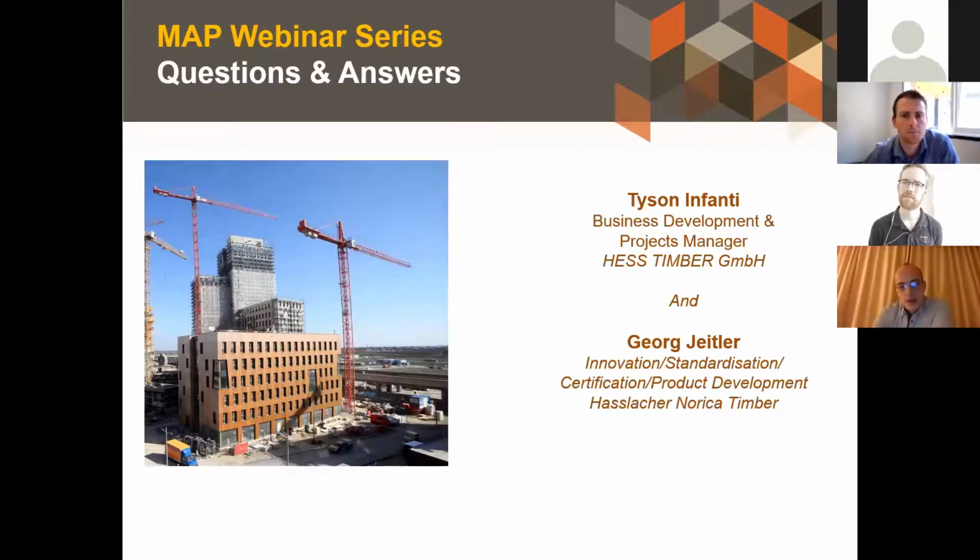This composite floor has some advantages. On the one side, it's the vibrations, because you get better results in vibration. Because of the mass of the concrete, you get very good sound insulation, because timber is a little bit poor in the deeper frequencies of sound insulation, and so with this concrete slab of, I think, 12 centimeters, you can handle this very well.